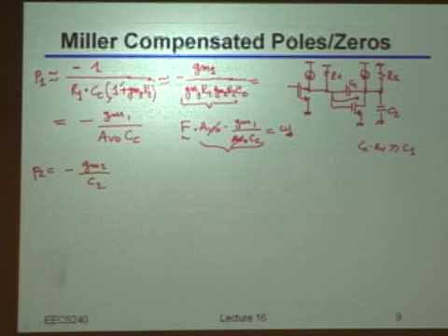So before that capacitance acts, you have an inverting stage. We would have just a common source, right, if the capacitance is open. For an input variation like that, I would get an output variation like that.